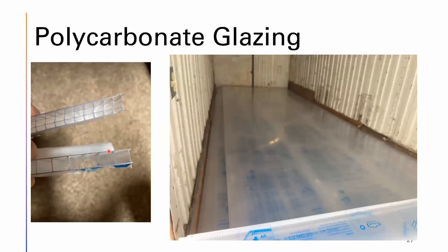So here's something else. This is the difference between a 2-layer, down here, this is what just about every commercial grower, 80% of growers, are going to use, the 2-layer polycarbonate. This is the 4-layer. It gives you 3 air pockets. And as I recall, I'm just ballparking, I'm thinking it's around a 56% increase in R value. It's not like 3 times the R value, but you get a noticeable difference.